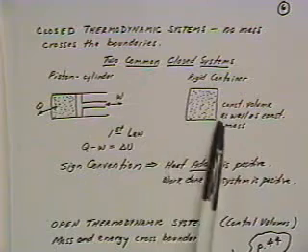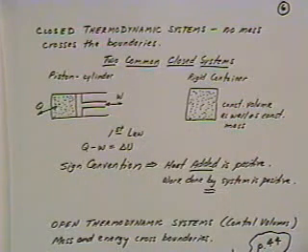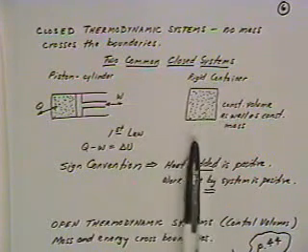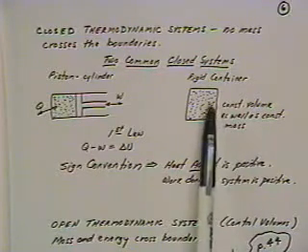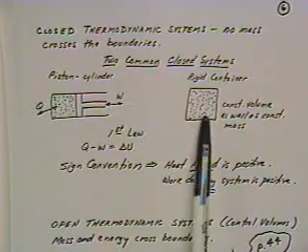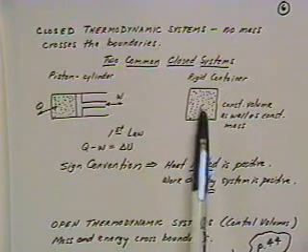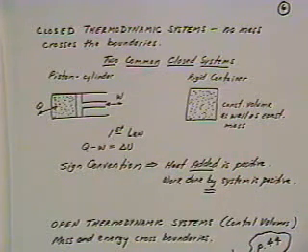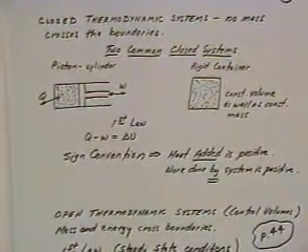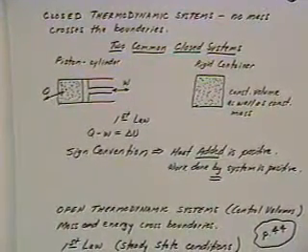The other type of common system that you'll run into in solving first law type problems will be systems that are constant volume as well as constant mass. This is just similar to the problem that we worked on the ideal gas law earlier, and that is we've got a rigid container that's a constant volume as well as constant mass, and so we'll be doing something to this, heating it, cooling it, or something of that nature, so that we will be using the equations for the first law to come up with the changes in internal energy or heat transfer or whatever.